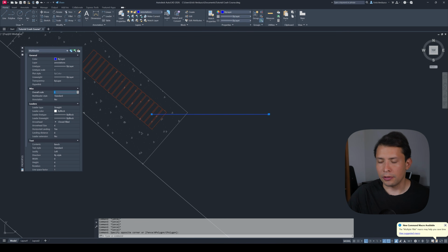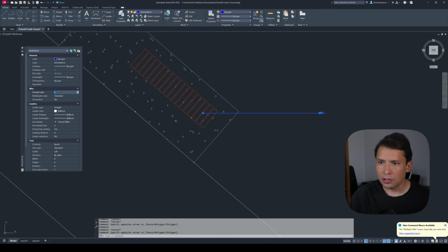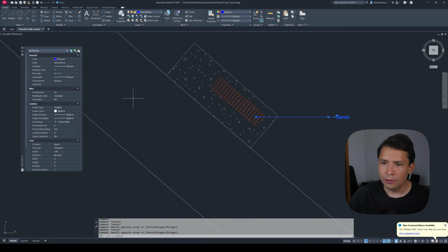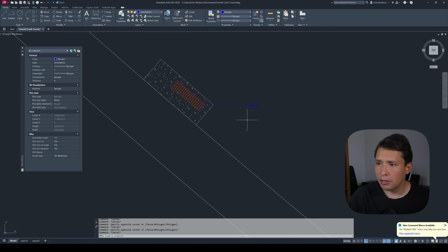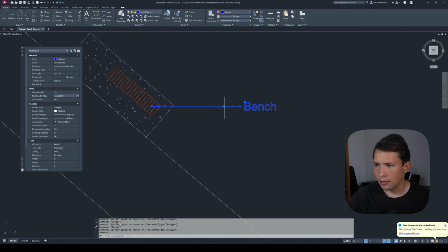Here on the properties, you can change the overall scale to 5. As you can see, that has made it bigger. Or you can change it, for example, to 30. That's going to give you a better size for this scale. And of course, if you create styles, which is a little bit more advanced, you can manipulate exactly the type of arrow that you want, the size of the text, the colors, and make them very personalized. For now, we're going to do it this way, and I'm going to change the overall scale to 75. I think 75 is going to work well.